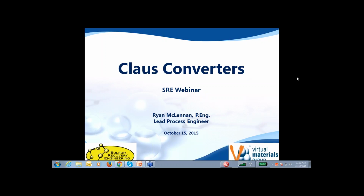Today's webinar focuses on Claus converters, a very important process unit within the sulfur recovery unit. Here is the driving force for overall sulfur recovery, where we react H2S and SO2 to form elemental sulfur in the vapor state. After a converter, we have a condenser where we take the elemental sulfur in the vapor form and produce essentially the final product in the SRU, which is liquid sulfur.